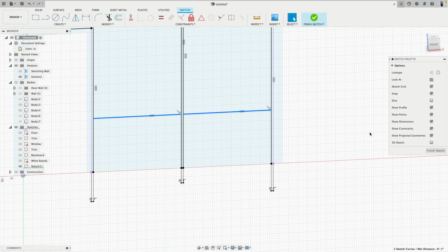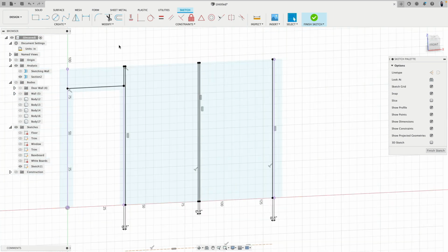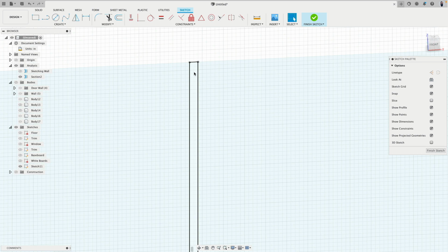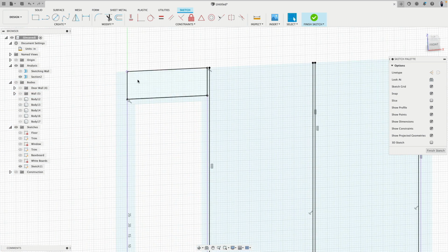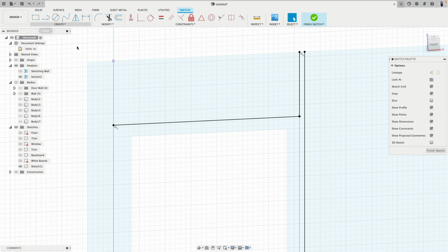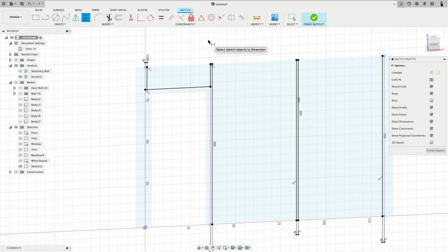Escape. And then these two lines we make construction. And look, I dragged these actually out. So these guidelines are still working, but they are actually just off our canvas here. Now you see with these lines, I have profiles. This is actually my first, my second, my third, and I need also here a fourth one. So I'm just drawing a line here, press D, 1 inch. Cool. Okay. So these are the vertical boards.